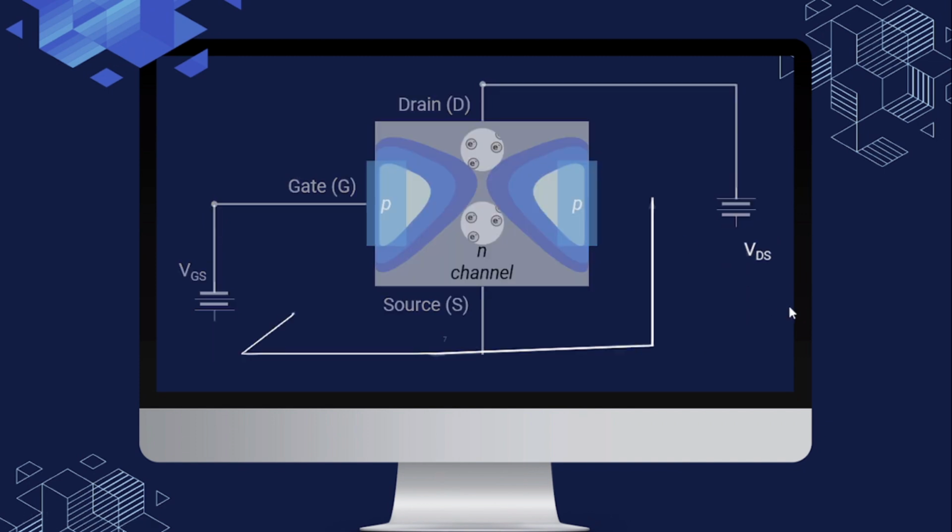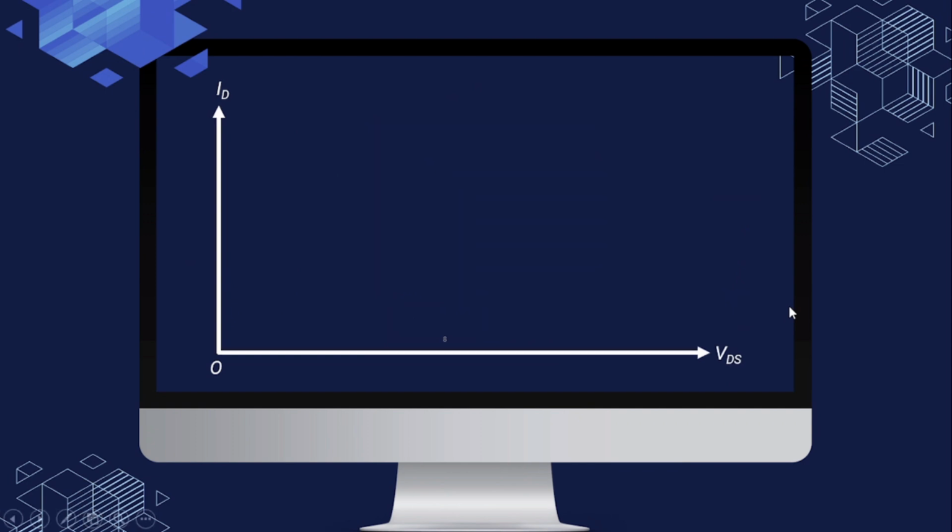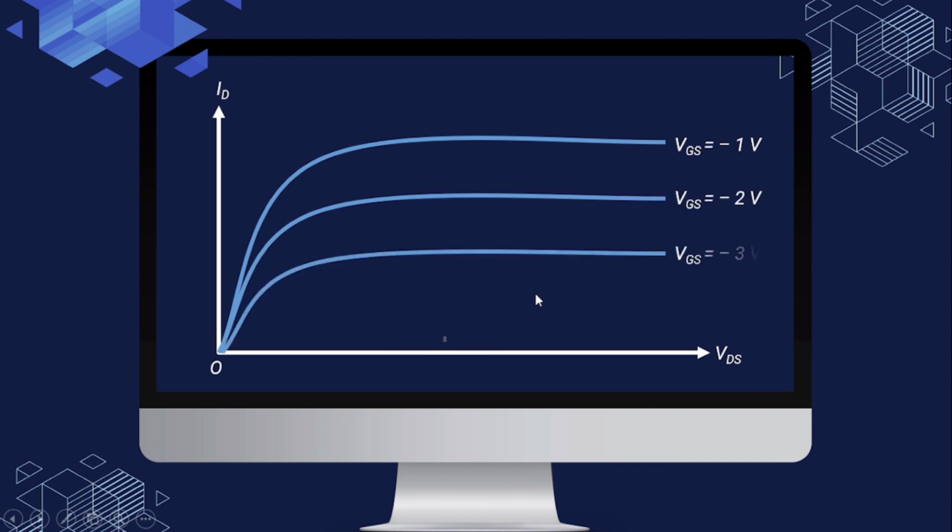The graph displays the relationship between ID, the drain current, on the y-axis, and the drain-source voltage, that is VDS, on the horizontal x-axis, for different values of gate-source voltage VGS. This is the linear region where the JFET behaves as a resistor. The current increases linearly with VDS, the channel is not pinched off, and the electrons flow easily.